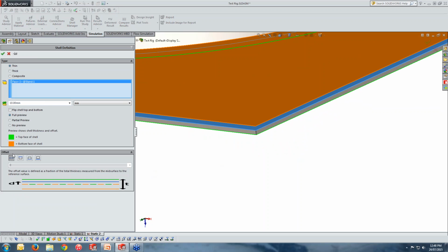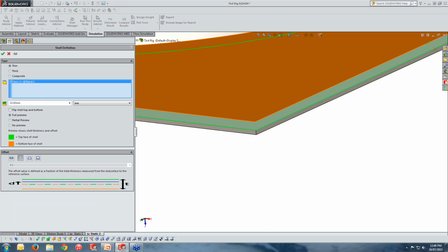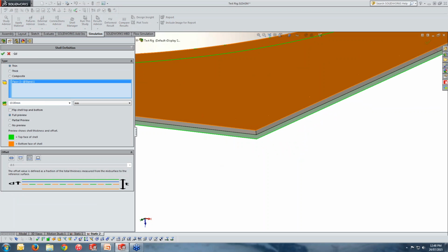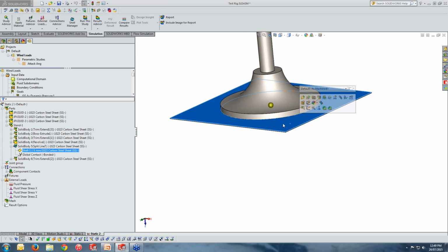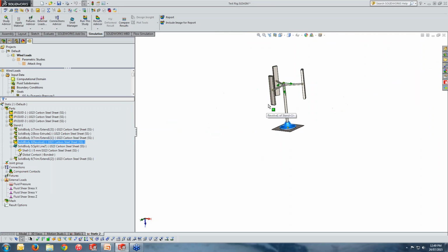Now I can go to the offset scheme, make sure it is located in the correct direction. So the thickness should be 5, and right now the orange and the green planes are simply showing us the thickness of this shell. Clicking OK, and I've converted my model to a shell here, solid here, and beams on here, again solids on the other components. Alrighty guys, now material setup and beam joints are set up.